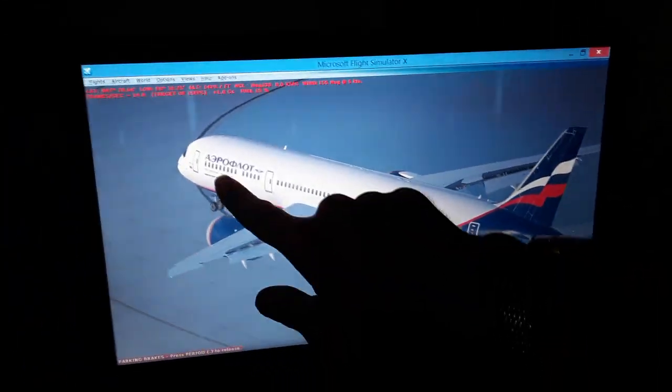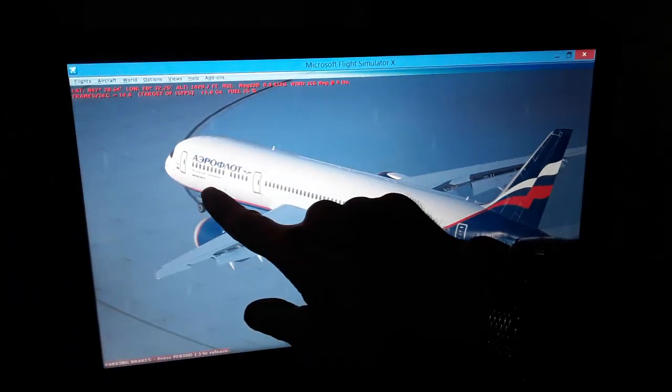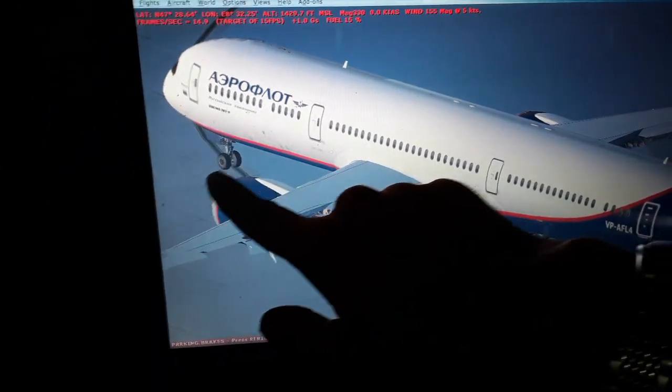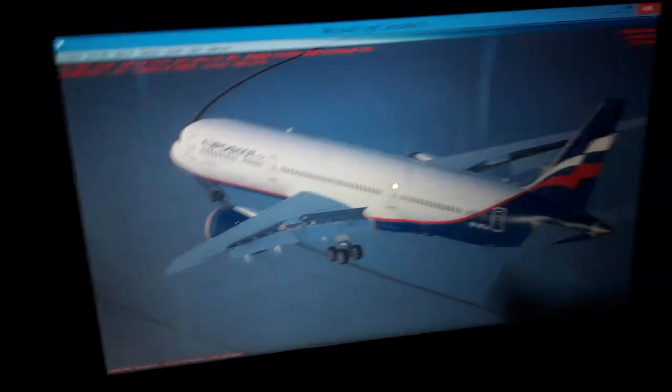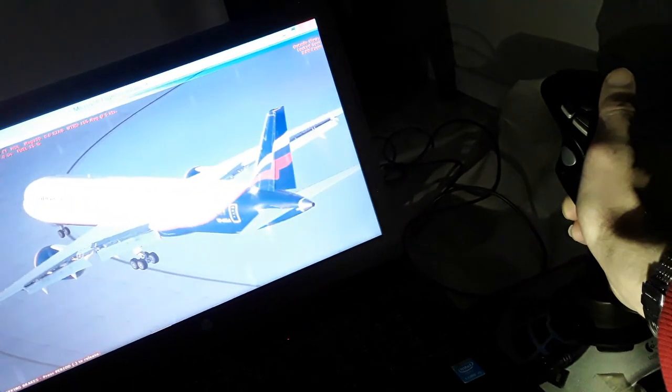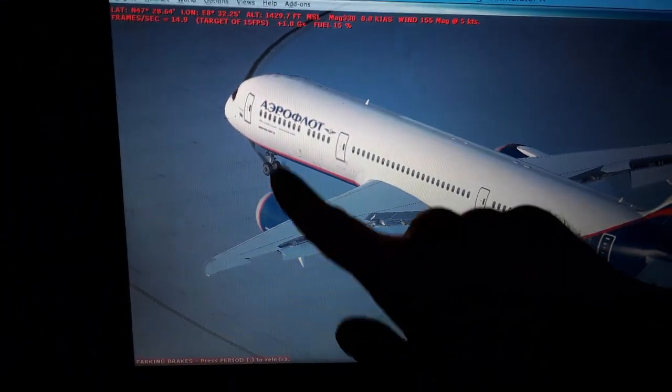It also controls on the ground the nozzle steering. So we can use on the nozzle steering on the ground 76 degrees left and right deflection from 0 to 45 nautical miles per hour. In takeoff we have the rudder aerodynamically effective, so it decreases automatically from the computers above 45 nautical miles per hour.